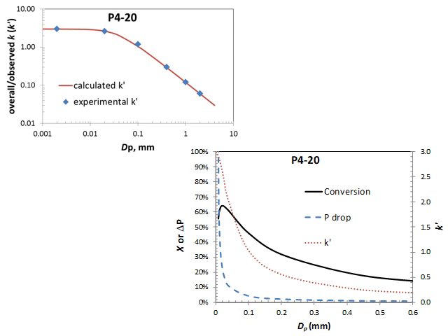Here we are plotting x, or the pressure drop, versus dp, and we are also plotting K prime. Of course, we only need to plot x versus dp, but I'm also plotting the pressure drop and K prime to understand what's going on. So again, at very small particle size, K prime is at its maximum value, or it equals the K of the surface reaction sequence. However, at very small particle size, the pressure drop is very large.